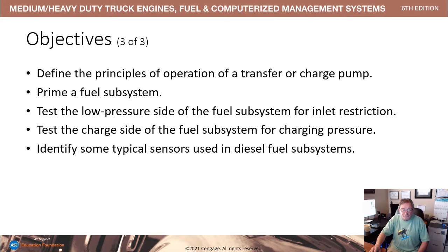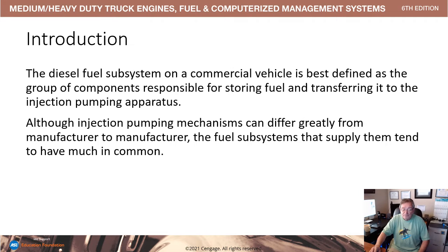Define the principles of operation of a transfer charge pump, prime a fuel subsystem, test the low pressure side of a fuel subsystem for inlet restriction, test the charge side of a fuel subsystem for charge pressure, and identify some typical sensors used in diesel fuel subsystems.